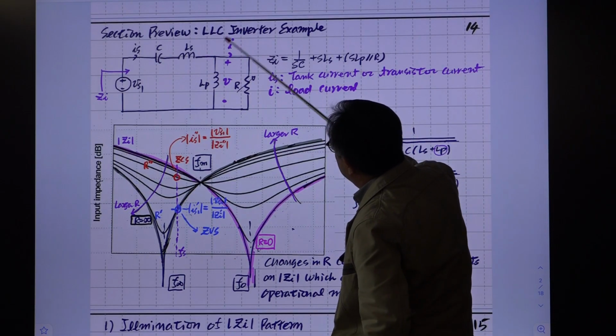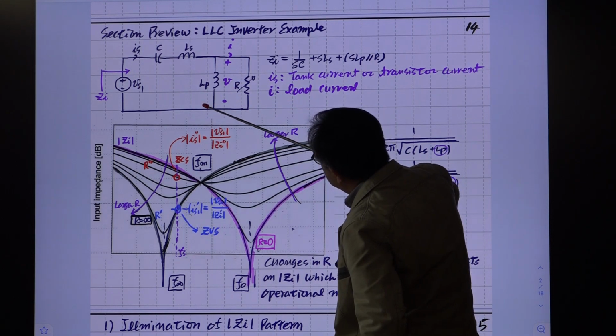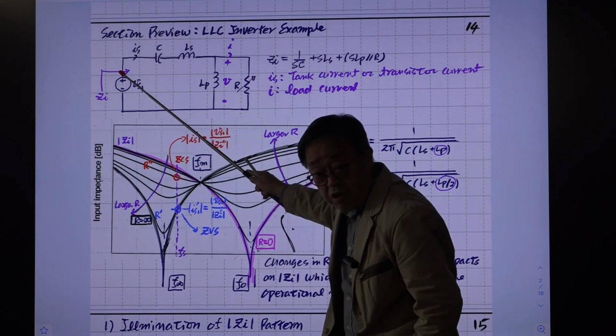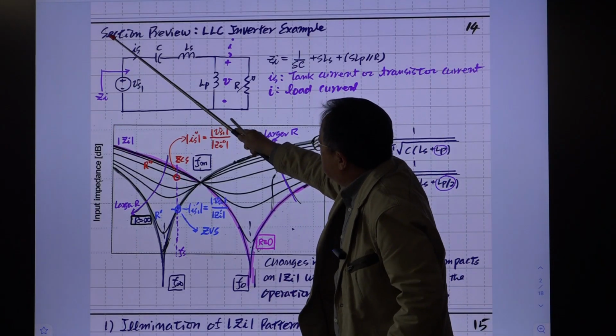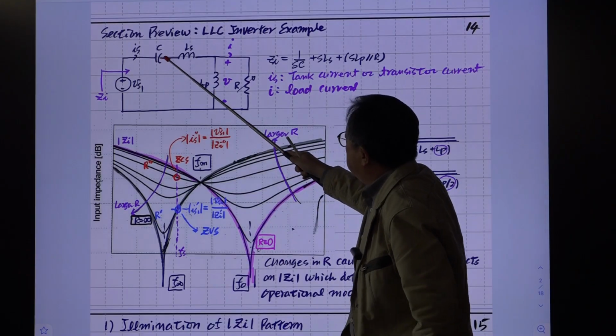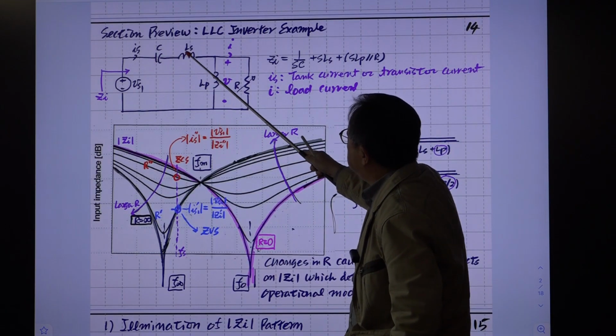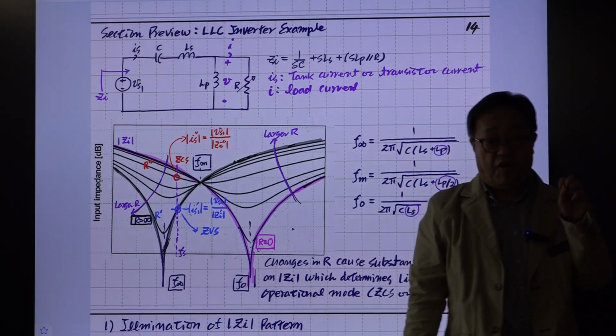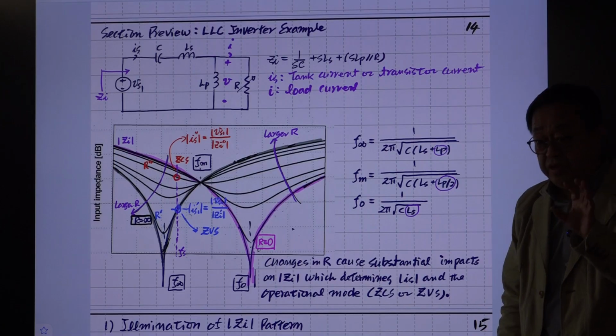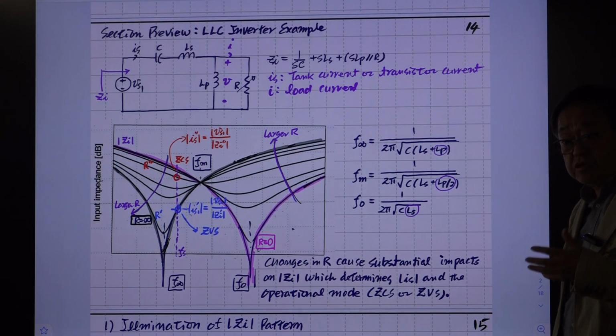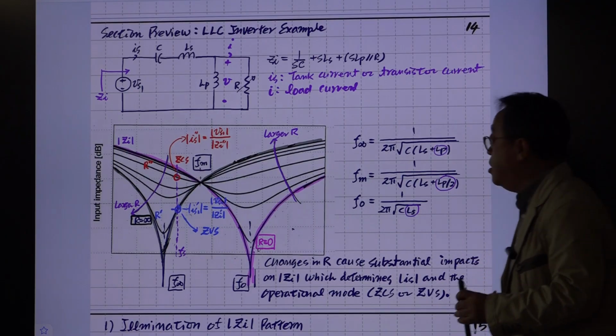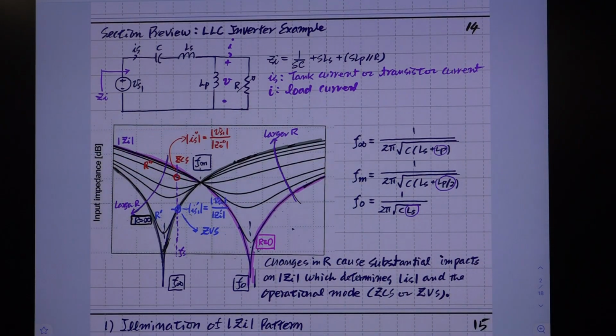Some of it will be the load current, and then it comes back through the switch network, inside of this bridge network, and passing some parasitic resistance in there will create the conduction loss. So conduction loss is very important. We are only considering conduction loss in these resonant converters. We assume the switching loss is negligibly small compared to the conduction loss. Okay. So knowing this is very important because of that. With that information, you can decide the magnitude of the tank current.